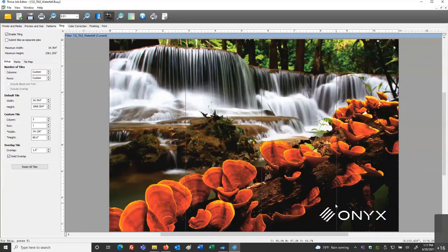We can drag these tile column lines, or if we click in that panel, number 4 will appear in my column, and I could also change the size here. So again, if I click in column 3 or column 4, I can control the information for that line. So I could also drag that information, or I could type a value in.